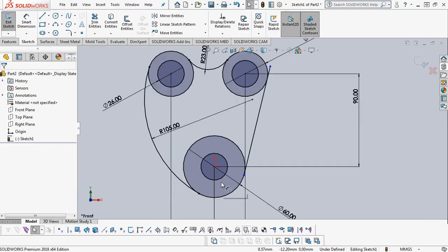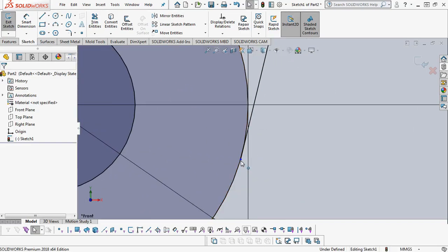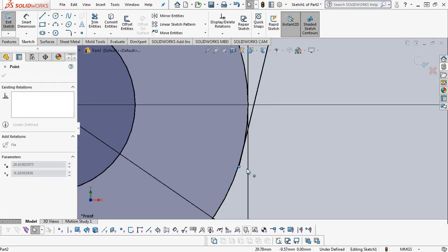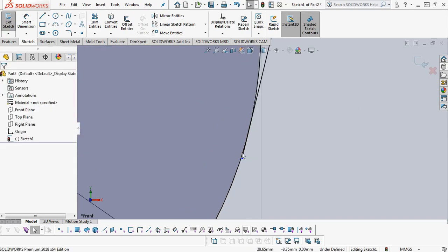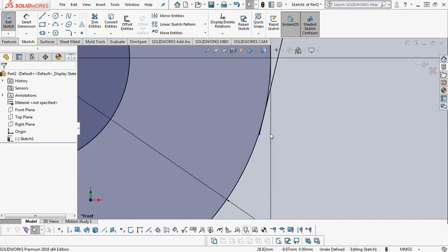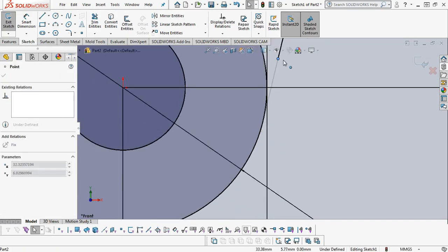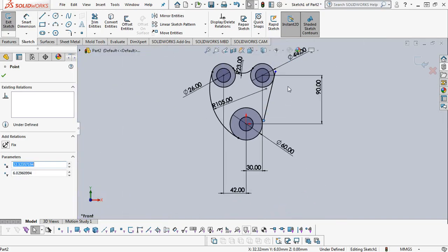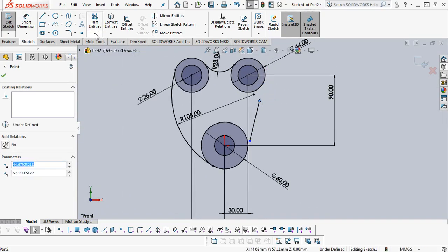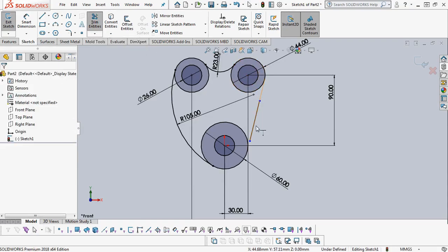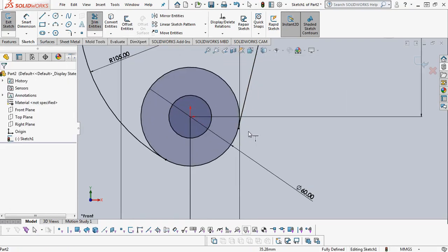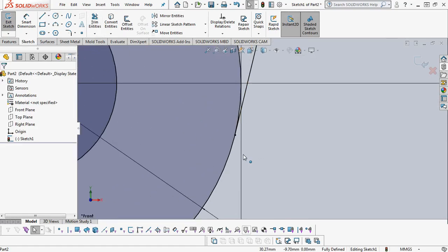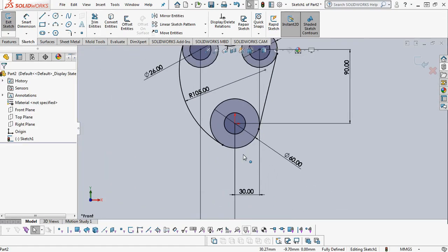So now if we select, in this case, this line we don't know it is touching or more, so you have to zoom in and check. Otherwise, easiest method is go here, drag inside, just say extend, so the constraint is done. No need to give additional dimensions for that line. The tangency between the two circles is enough to constrain that line.